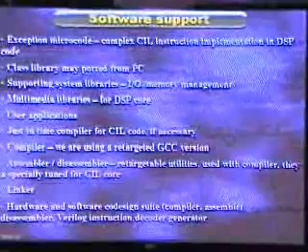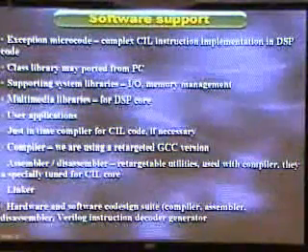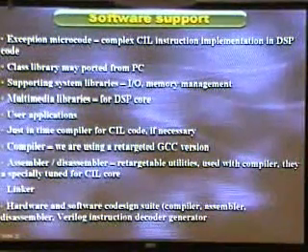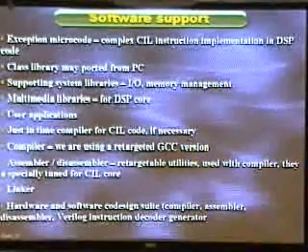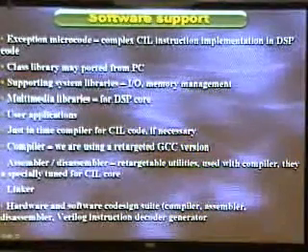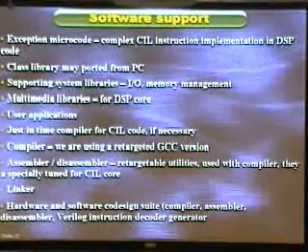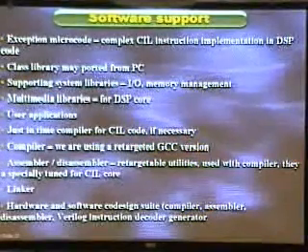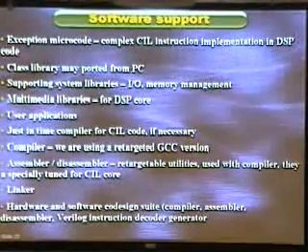This is our full software support, which consists of exception microcode for complex CIL instruction implementation in the DSP core. The class library may be ported from PC, supporting system libraries, input-output, memory management, and so on. Multimedia libraries for the DSP core, for DSP mode, and user applications, and a just-in-time compiler for CIL code if it's necessary.